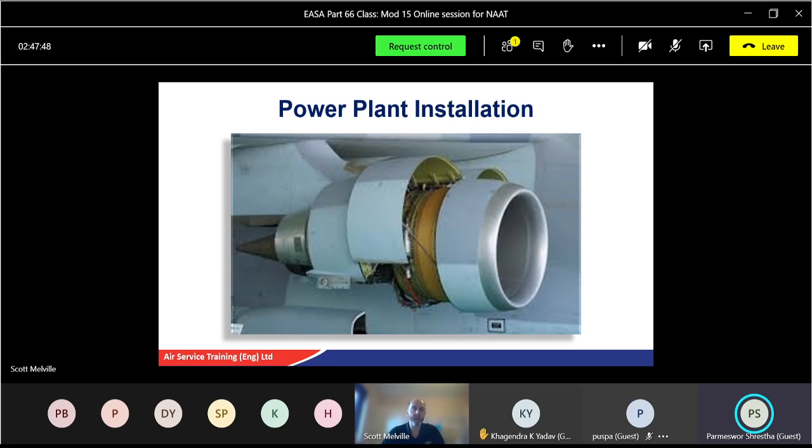So what would be bigger, the crankshaft gear or the drive shaft gear? Drive shaft? Yeah, drive shaft's always bigger. Depending on the reduction gearbox you've got, depending on the system, a standard spur gear would be a small crankshaft gear. So basically the crankshaft is going that fast that if it was the same 1-for-1 ratio, the rotor would be going too fast. So we need to do reduction gearboxing, and I'll just highlight myself.